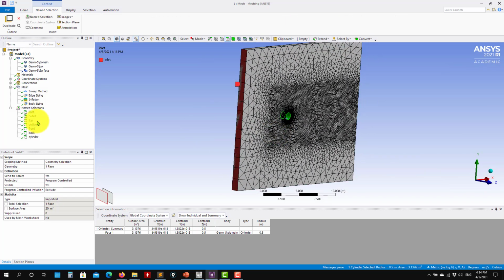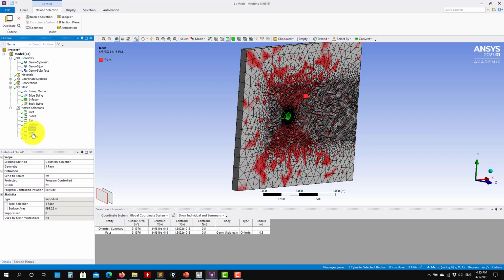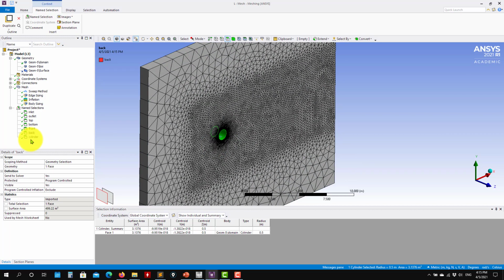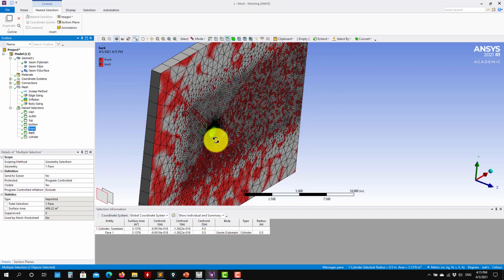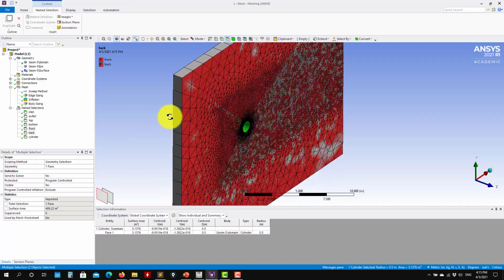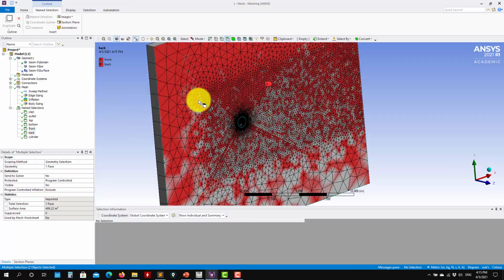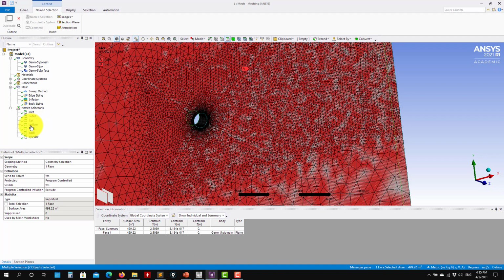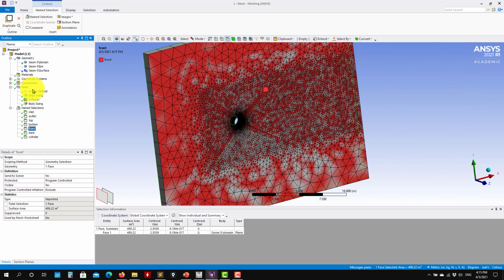Remember to set up your boundary named patches, and important, these two faces you also need to set up. If you don't give names to these, Fluent will automatically group everything. But when you start to set up your case in Fluent, remember that this needs to be symmetry and symmetry in the setup. And it's recommended to have the faces independent. So that's all, this is the case, and this is the mesh.